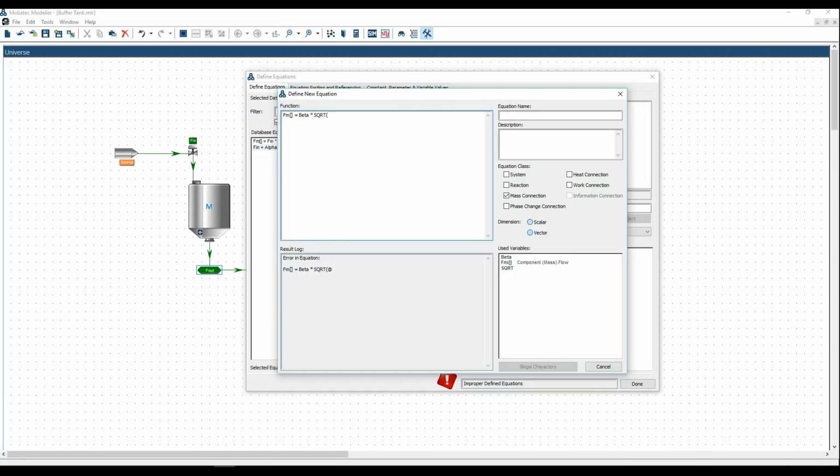In order to use the liquid level variable, we have to type prefix or dot L. This prefix signifies that we are going to use the origin variable, as buffer tank is origin system of this connection. If we are about to use the target variable, the variable which is located in the target system, we would use tar.l.